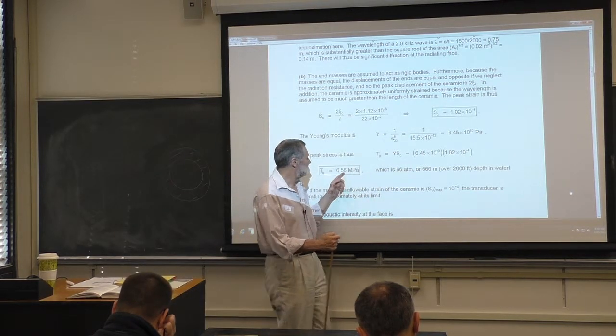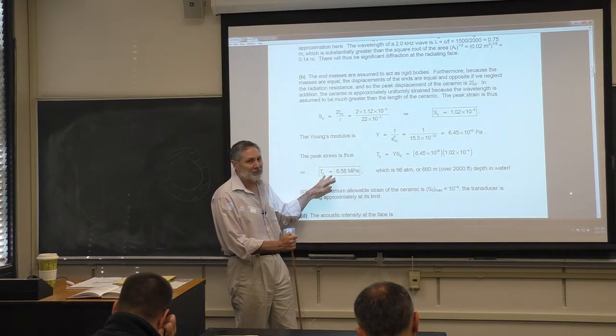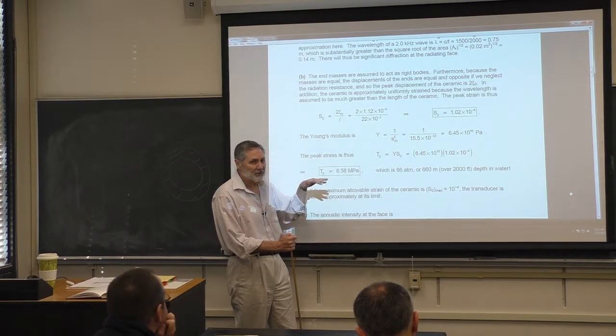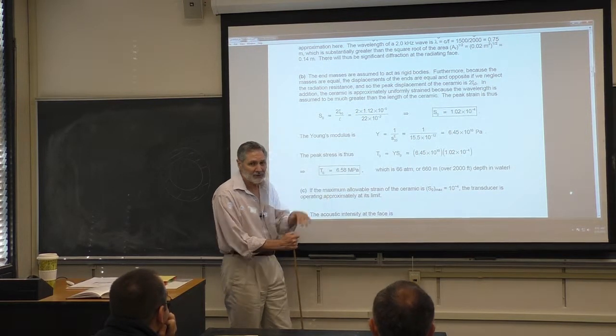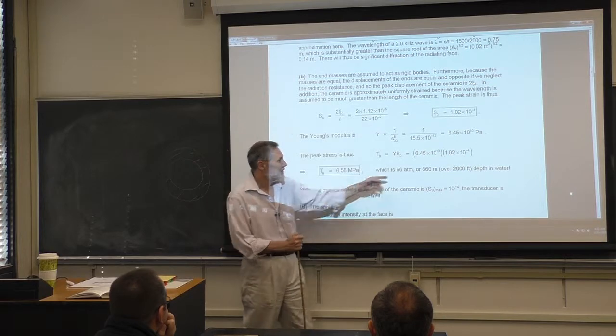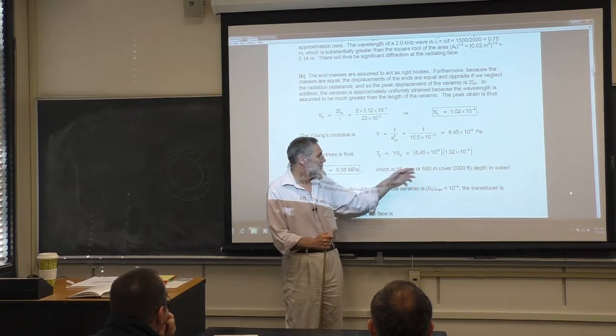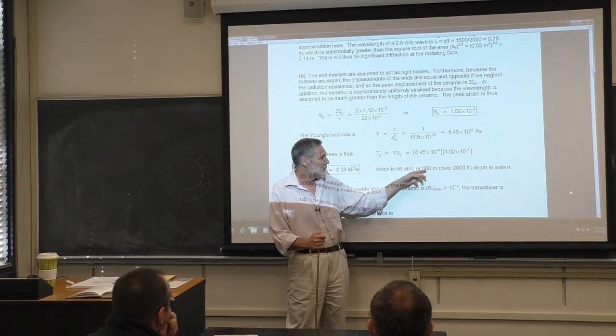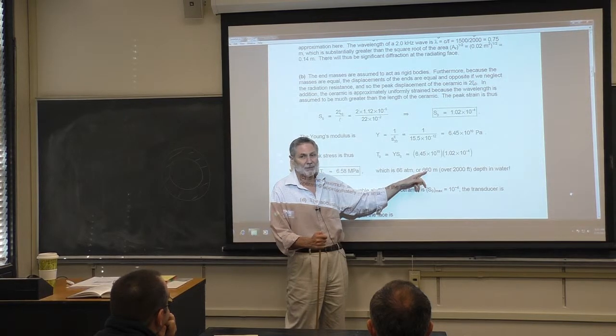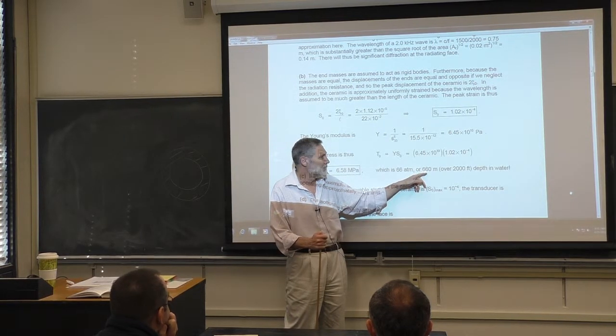This is about 66 atmospheres, and you remember in water there's 1 atmosphere for every 10 meters, right? So this stress is the same as the pressure at a depth of about 660 meters.